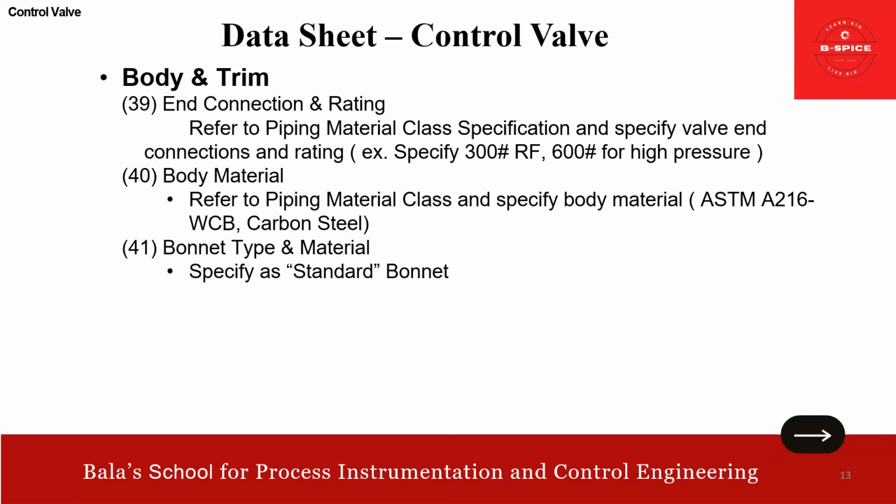Which we need to consider an extension or fin bonnet. Where is this extension or fin bonnet actually used? This is used when the temperature exceeds 200 degrees, or is below 0 degrees. In this case, we can use the extension or fin bonnet type. Friends, just remember, of course, you need to align with the manufacturer recommendation.